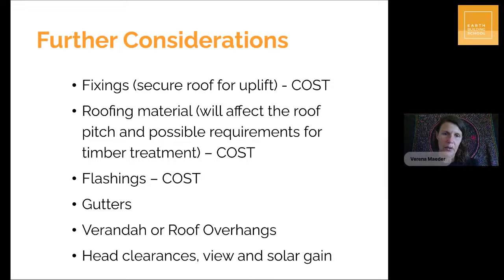And very important that you put gutters on, especially if you have an earthen building. But for any building, it's good to get water away from your facade. You might want to think about roof overhangs or verandas, for usability, for shade, and so forth. And the veranda roof also has beams and rafters, so you would have to size those as well. And then you're also looking at the angles, the pitch of the roof, how steep it is.